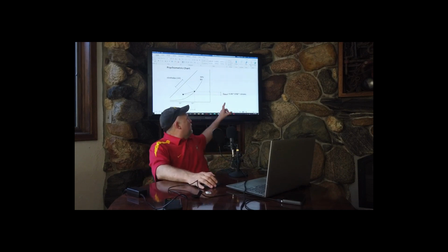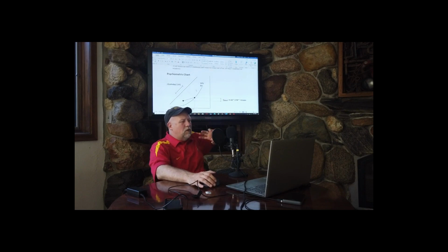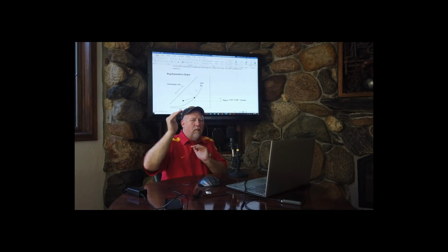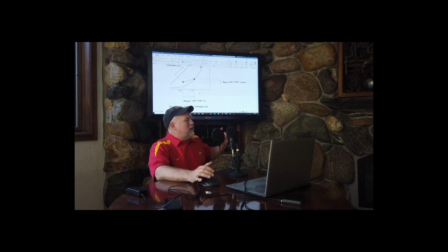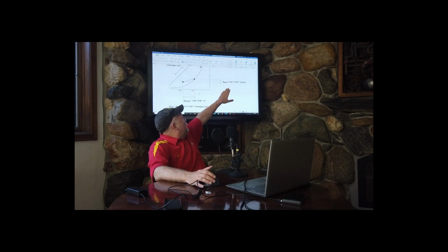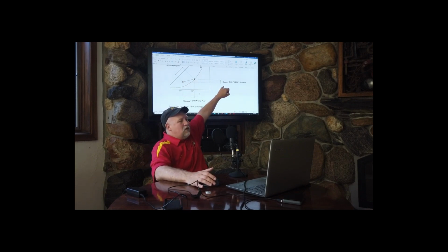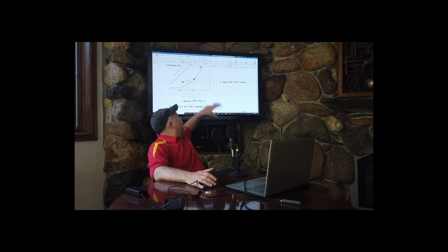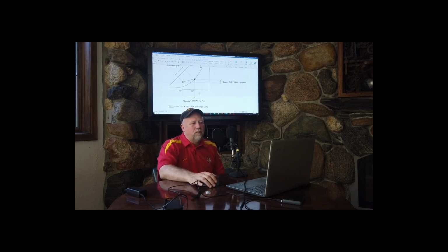Anytime that we use that psychrometric chart, we can use it to find the total energy change from one condition to another. Here, this is graphically representing those two equations that I gave you earlier. Let's say that we have a mixed air condition, or just a room condition, and a space condition. As I cool that air down, I will lose both sensible energy and latent energy, and I can plot those on that chart, use these equations, and come up with the total energy change.